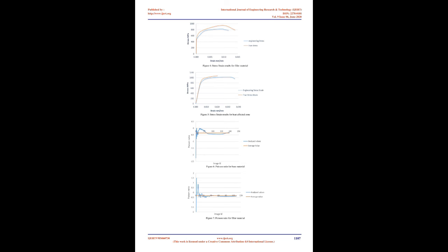Yield strength for base material, approximately 727 MPa, is found to be slightly higher than the designated strength of 690 MPa. Figure 4 shows the same plot for filler material of G46 and its strength is found to be approximately 500 MPa, which is again a bit higher than the designated 460 MPa. The joint remains undermatched as filler material strength is less than base material.